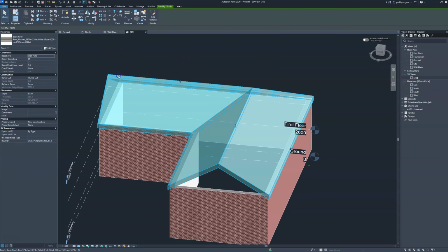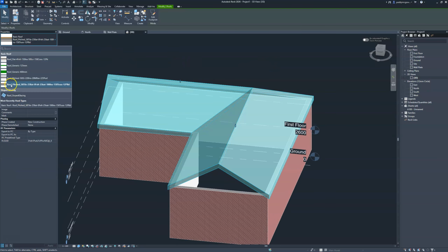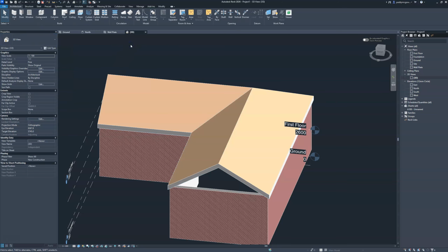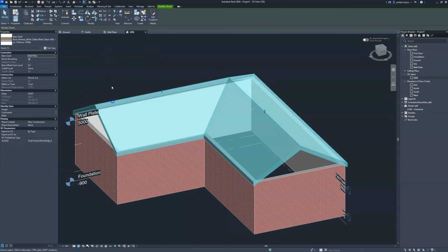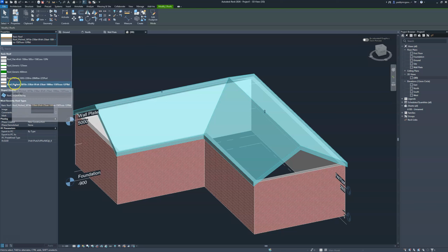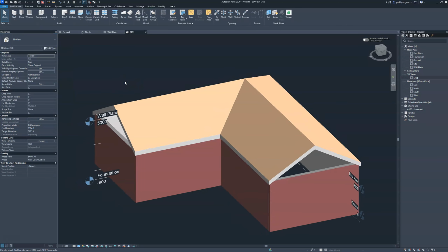The roof that I've chosen is this one. I've gone for 30mm tile, 25mm batten, 0 felt, 25 batten, 100 insulation, 150 truss, and then 12mm plasterboard on the inside. That's a standard one, by the way. I don't think I customized that roof.